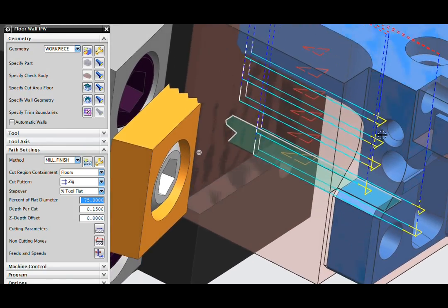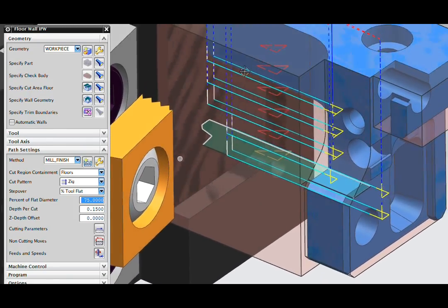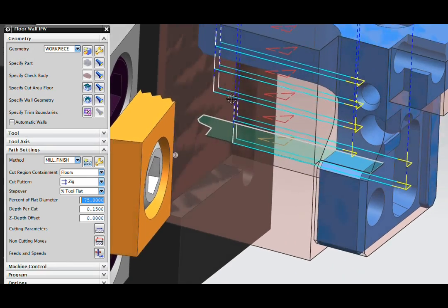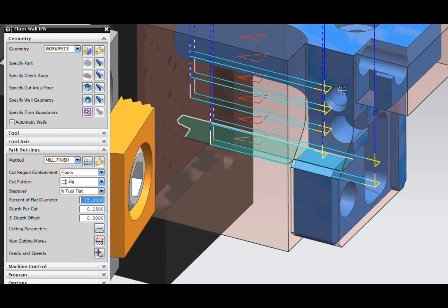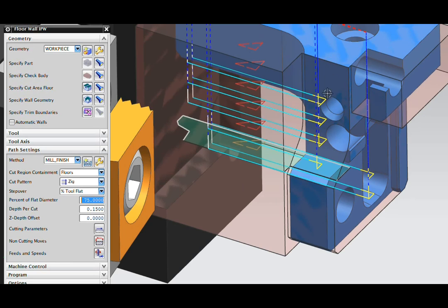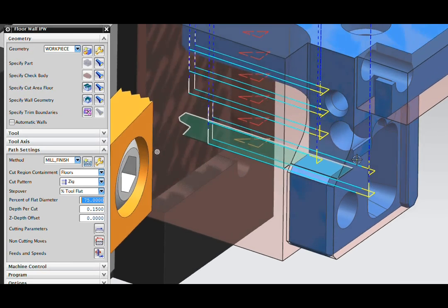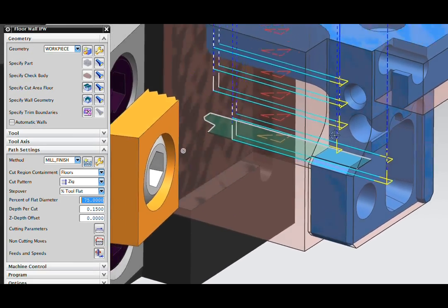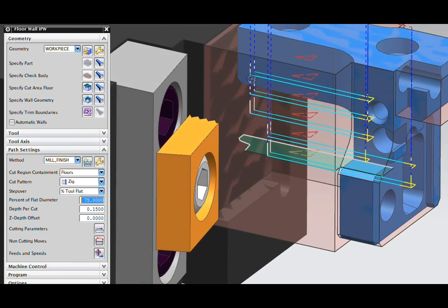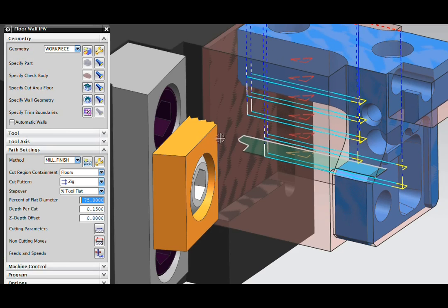That looks much better. You can see how the floor wall machining command keeps track of all the parameters in the machining process, though. Here it starts the passes farther to the left because it knows that that stock's already gone. As I get to the bottom, though, the passes have to come further out. It's the same situation with the check stock. As I get closer to my clamp, the passes can't get in as deep.